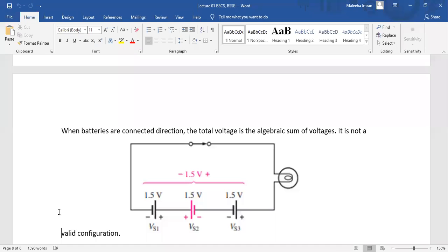लेकिन फर्ज करें, मैं ये कहता हूं कि आपकी एक सर्किट के अंदर दो सेल्स लगे हुए हैं, एक 6 वोल्ट का लगा हुआ है और एक 1.5 वोल्ट का लगा हुआ है, लेकिन वो दोनों इस अरेंजमेंट में लगे हुए हैं कि एक का नेगेटिव दूसरी के नेगेटिव के साथ कनेक्ट है, तो क्या करंट फ्लो करेगा?